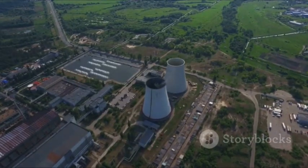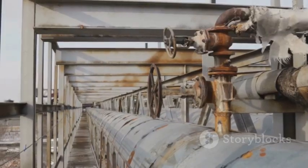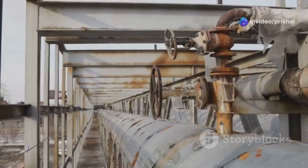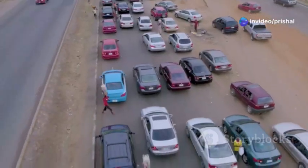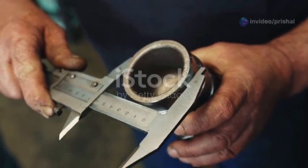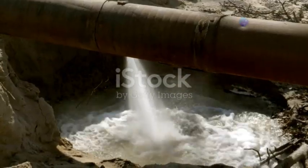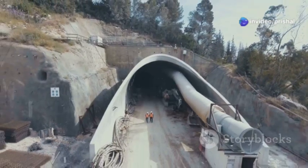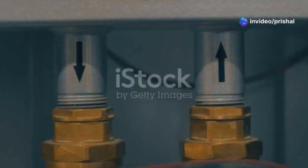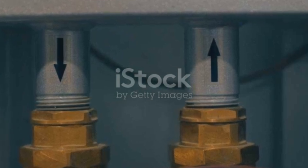That's where the penstock comes in. It's like a giant water slide for energy. The penstock is a large pipe that carries water from the intake to the turbine. But just like we wouldn't want a traffic jam on our energy highway, we need to make sure the penstock is sized correctly. If it's too narrow, the water will have to flow too fast, creating friction and losing energy along the way. On the other hand, if the penstock is too wide, it'll cost more to build and may not deliver the water with enough force to spin the turbine efficiently.